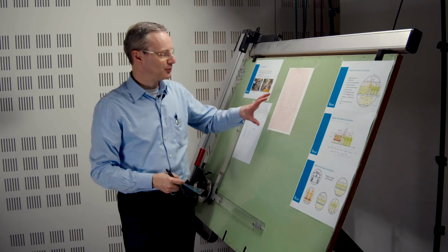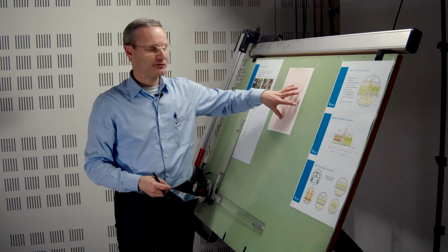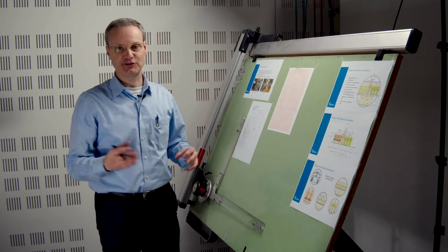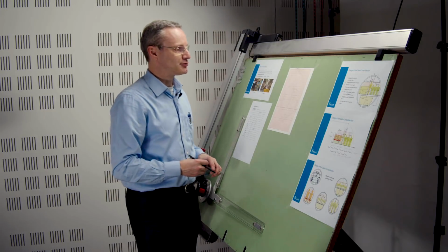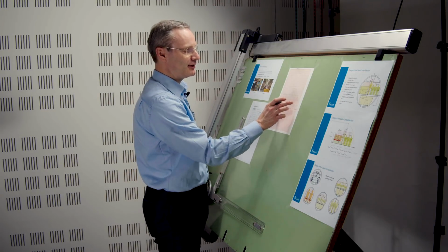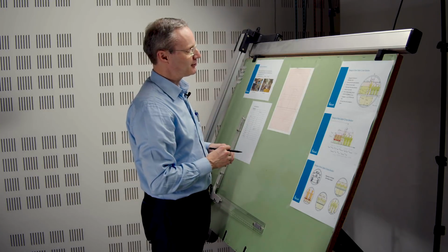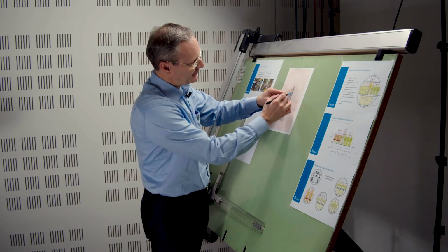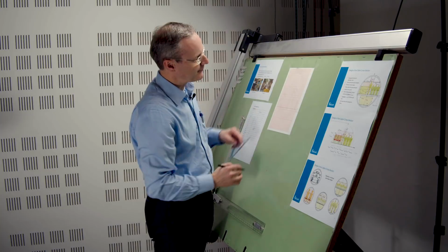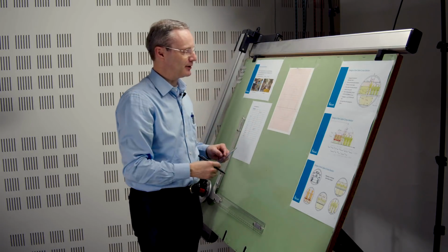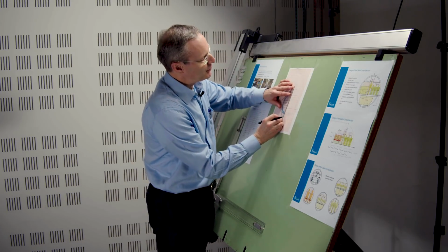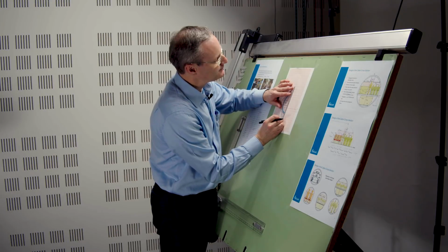In this case, we have an asymmetric division of the seats here. So it's a bit tricky to figure out where exactly is the other center line. But the best way to do this, make use of the center line that has already been given here. So make use of the vertical center line to measure that. I'm going to use my protractor again.